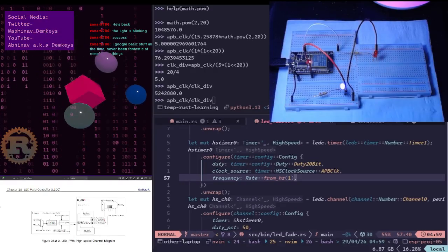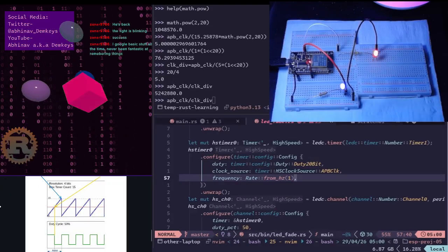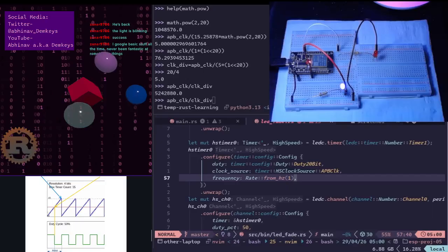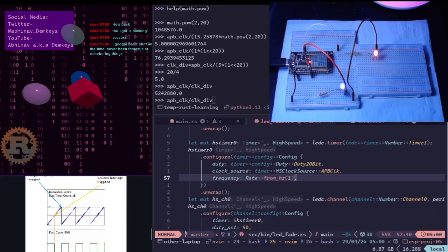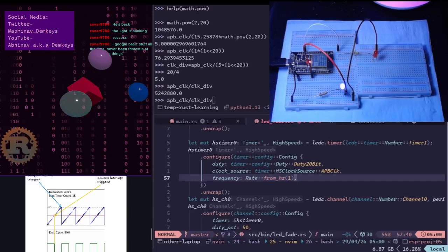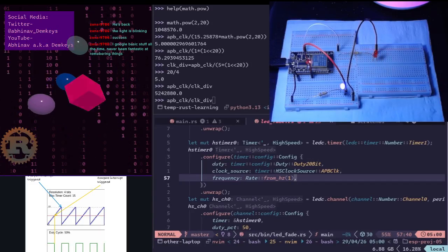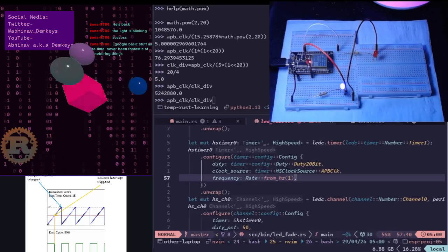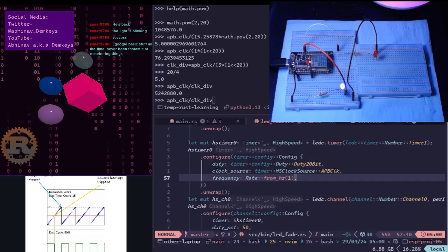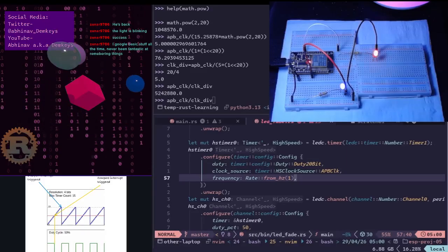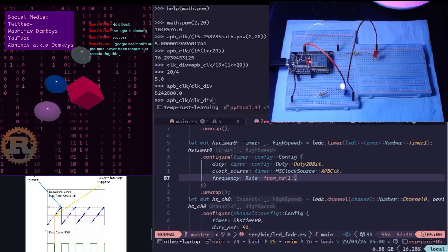I'm glad that I have all of these tabs open. If we come here, this is our count. This pulse acts as an enable signal for the actual PWM counter, the one that determines your duty cycle. The internal divider counter resets to 0 and starts over. Awesome. That's after the trigger.